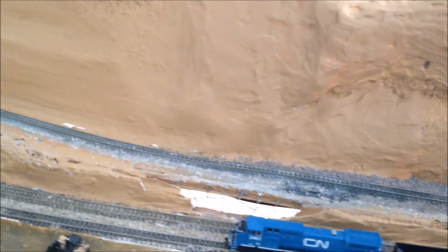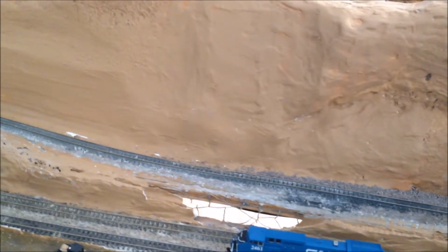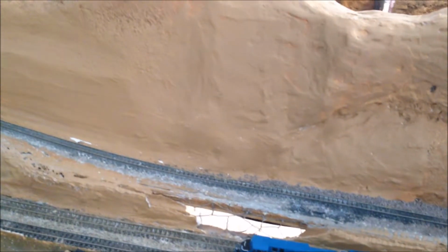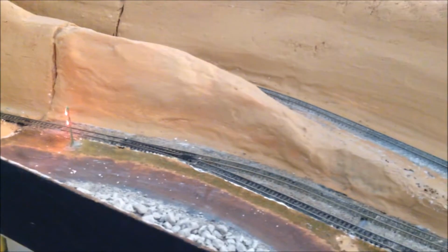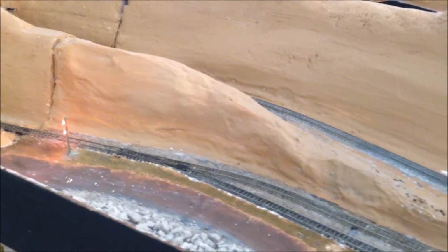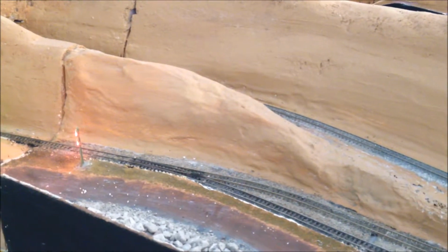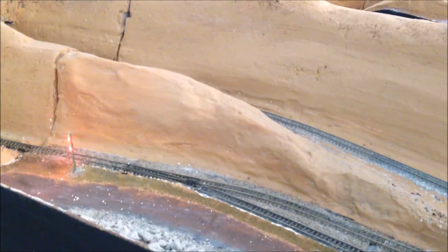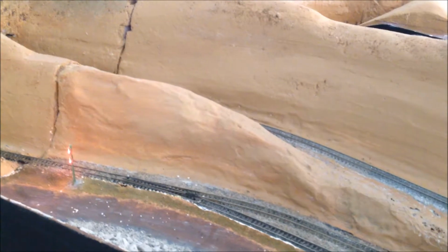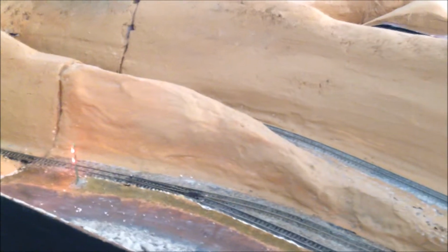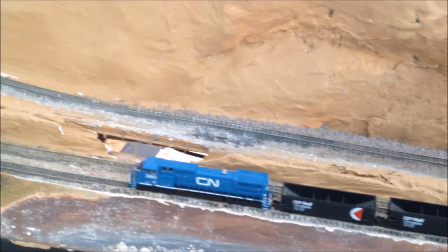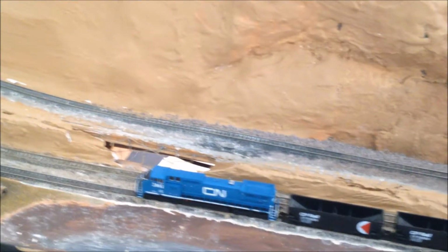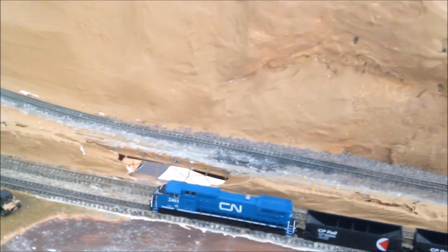So basically, around the layout you have a DCC bus. You have two wires that go all around the layout and connect to all the tracks. The turnout decoders are connected to the coil, whether you're using Pico coils or Tortoise motors. It goes to the decoder, then from the decoder two wires go back to your DCC bus, which is basically the track. So all the information is sent on the track, the voltage to run the train and the DCC signal, and that's how everything communicates. They all listen to see if you're talking to them.